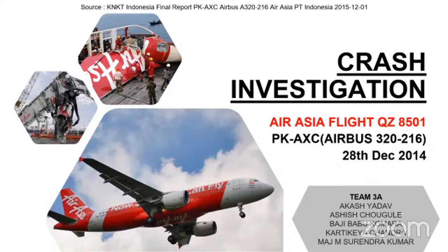Okay, one minute. Now, Ashish Chogle, have you heard the question? Yes, sir. Can you answer? Sir, actually, because of the autopilot reset, the rudder was shifted to 2 degrees. So it made the flight go out of control, and he gave some roll command, which brought the aircraft to 54 degrees roll. So it was not possible to bring it out of the stall at that point, sir. That's the first part of that question, sir.